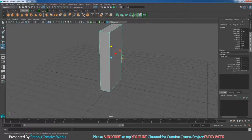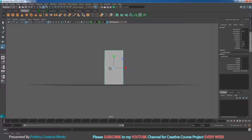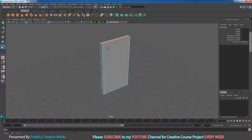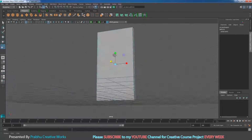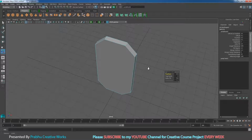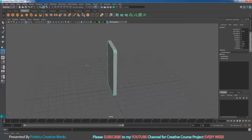So press R and scale in Z. I want it very thin. So like this. So now I want to select all my edges. So the corner edges. You want to select all 4 corner edges using shift right click and choose bevel edge. So now I decrease my fraction amount. I increase my segments to 5. So like this. So right click and choose object mode.